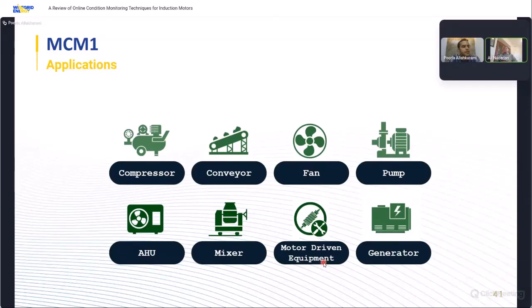Actually, based on the measurement input range, we can measure all types of motors and generators. For the generator specifically, we can have a vibration analysis, and we have the frequency spectrum of the vibration in the generator, and we can measure the current of the generator, and we have some parameters like unbalance or THDs and power factor of the generator to assess the condition of the generator.